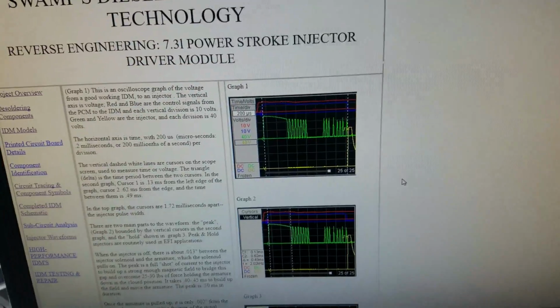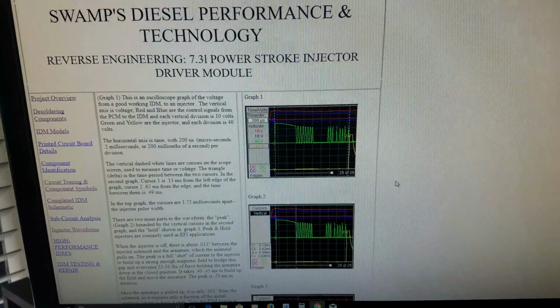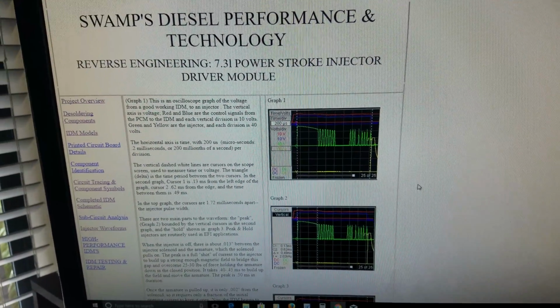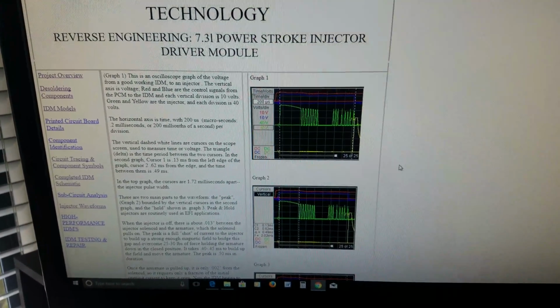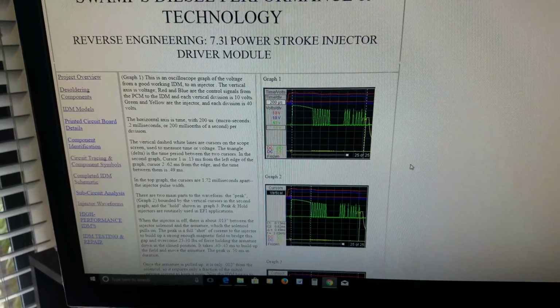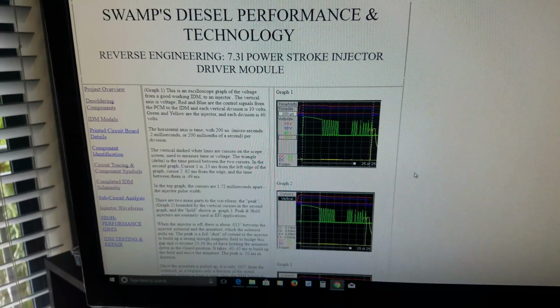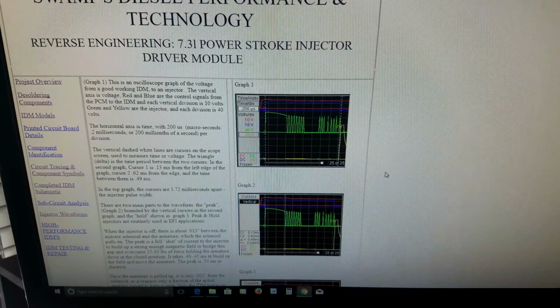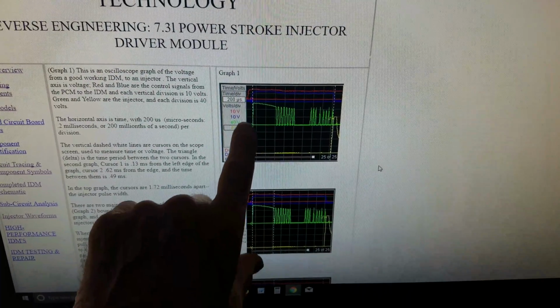This is the waveform, and it's actually quite complex. These hydraulic injectors have a coil in them, a solenoid, that has approximately a 3-ohm resistance. So if you apply 110 volts across 3.2 ohms, you're going to have up to 34 amps of current, which if left continuous would burn out the coil. So the electronics of this are fairly complex.